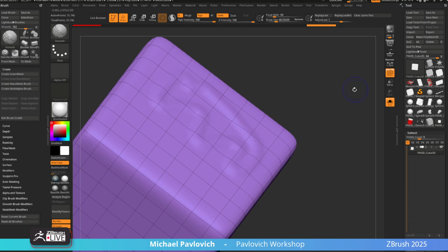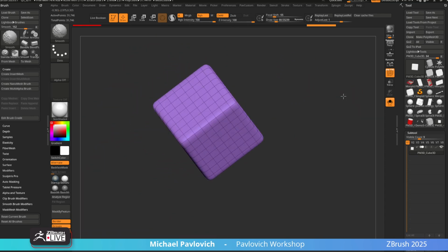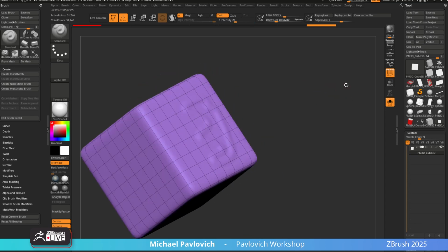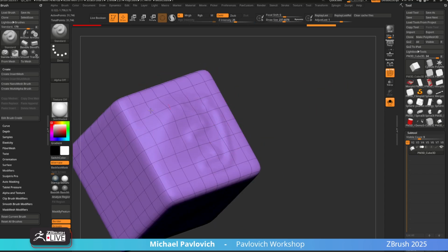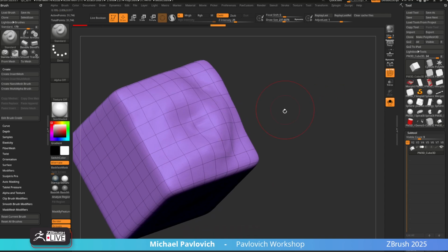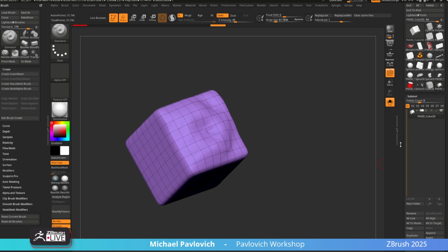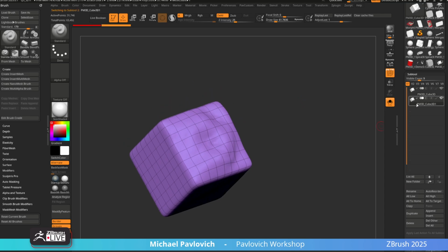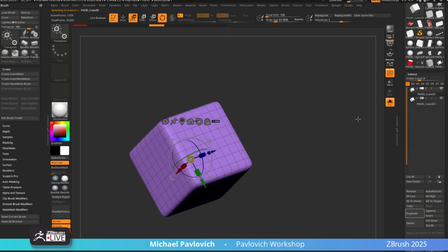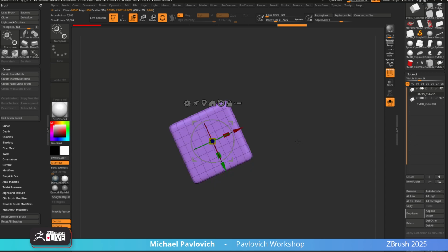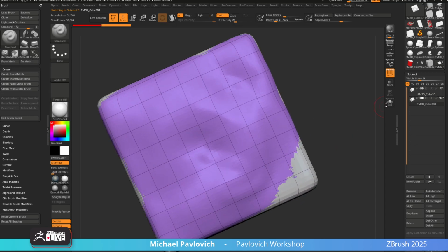Now, of course, if you hold down Shift on your camera, it's going to switch back to the world axis snapping. Now, this gets a little trickier if that surface is all undulating and rounded. I don't have a surface to snap to. You may have to get creative and maybe keep a version of your cube that's flat. So you can say, hey, I want to sculpt on this cube, but this cube has my easily alt-tappable, shift-clickable, isolatable surface. So now you can go through here in solo mode and look straight down on that surface. If that makes sense.